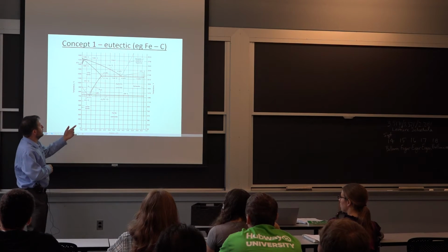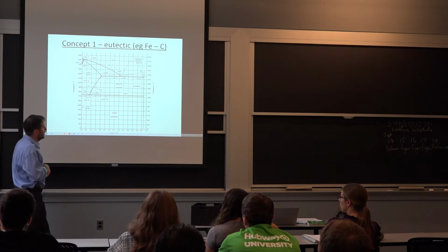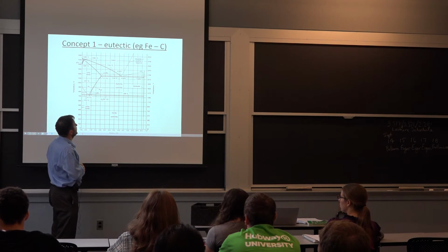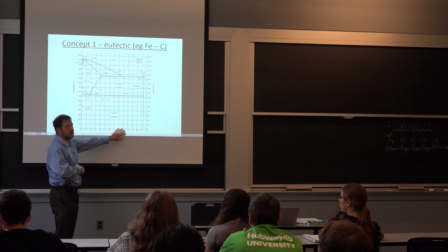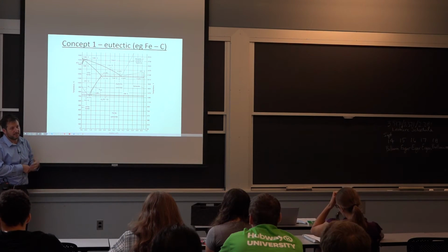And that is essentially the biggest technological change, and the reason why traditionally we've been using cast iron, and we still do use cast iron for price reasons, and the fact that you can do it at a lower temperature using less expensive material and less expensive processing.